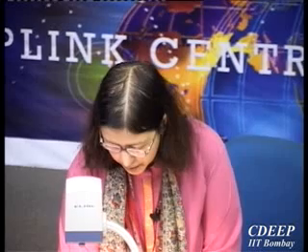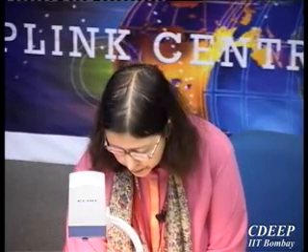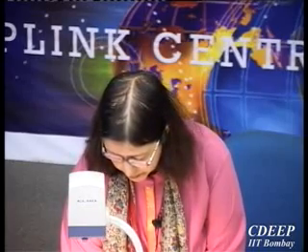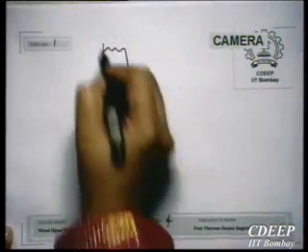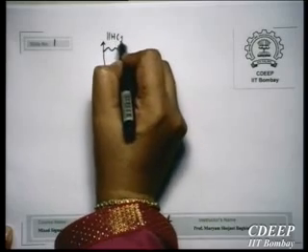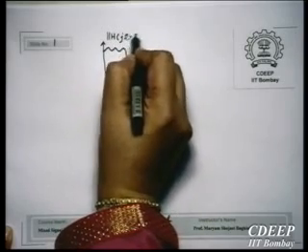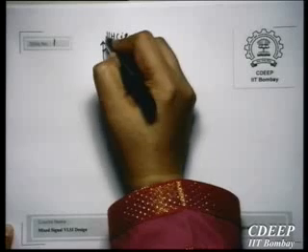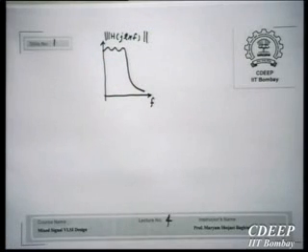So in the last lecture, one of the students asked about how this phase changes in the Chebyshev filter and how this rapid change in the phase happens when we have sharpness in the characteristic of the filter. See, when you have a sharpness, it means that your poles have high Q. High Q means that their real part is small compared to the poles which have smaller Q. Therefore, the question was, okay, so how does this affect the rapid phase change?